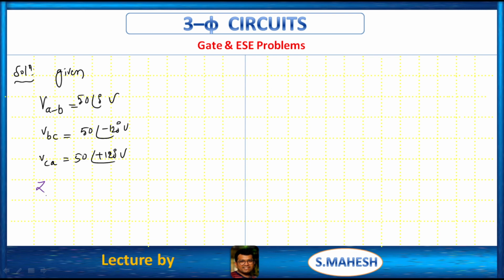Therefore, next, what about the impedances? Given that ZA'B' which is equals to 5 plus j4, which is equals to 4.64 at 38.7 ohms, like that ZA'C' which is given as pure resistive load, that is 5 ohms only, right? Next we have to calculate IA'B'.